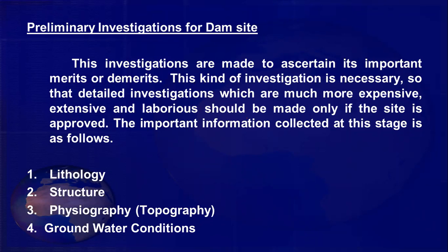Why is this preliminary investigation necessary? It is before the detailed investigation, because your detailed investigation requires a huge amount of cost, time, as well as manpower, right? Because the dam site is spread across various square kilometers.